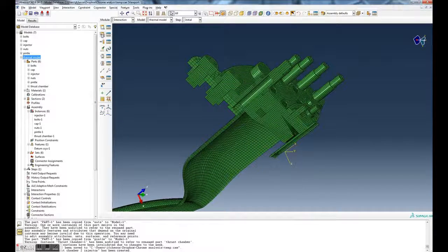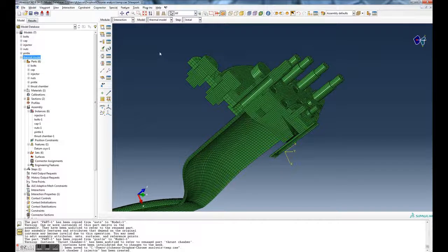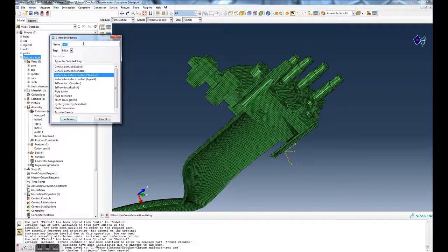And now if I step through all this stuff, here's the B matrix, right? These are the nodes 2 to 4, right? So, oops, dang it. I screwed that up. But, okay, the scatter vector is the same. So scatter vector is this. So I want to get from the global D rows 3, 4, 7, and 8. Those are the X and Y displacements for the nodes of this element. So that allows me to get B times the displacements. That gives me the strain. Then I just multiply the strain by Young's modulus, and I get the stress, and I print it out.